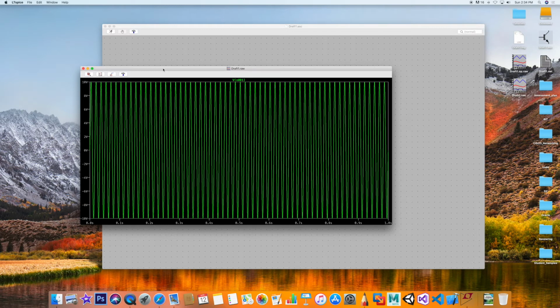It's very busy. But you can tell, you can get some information out of this, that the max peak voltage is 10 volt. So it's a peak-to-peak 20 volt, right? Okay. And notice your voltage division is 2 volts per division going vertically, right? And then for each one of these division is 0.1 seconds, and I have 10 of those. What if I go 1/10 of this, right? 1/10 of this will be 0.1.